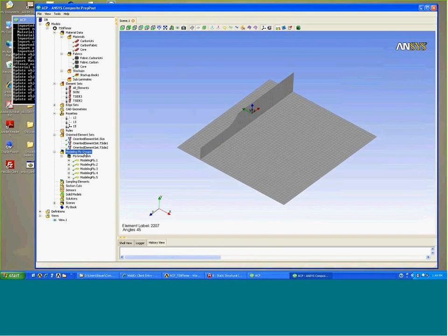Now, with the modeling ply groups, you notice I right-click to create this group and start building up the ply definition with respect to the oriented element sets. You can also import and export from a CSV file. So what I've done previously was to speed up the ply definition in our various regions. I built a T-stiffener model. I exported that. So let me import that CSV file now.